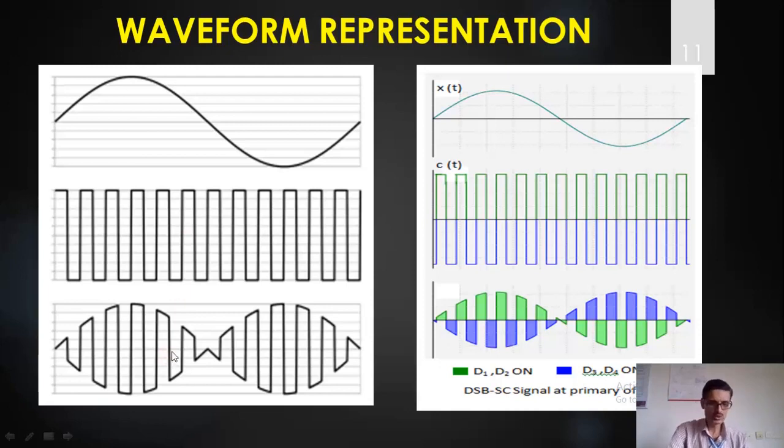As you know, the DSB-SC signal is generated by using a simple product modulator. So in this case I am using a ring modulator which works like a product modulator. Now if this is the positive voltage and the carrier has a normalized amplitude of -1, in that case what happens? Plus and minus, it is minus. But during the negative half cycle, because of the cross connection, the carrier phase will be different.